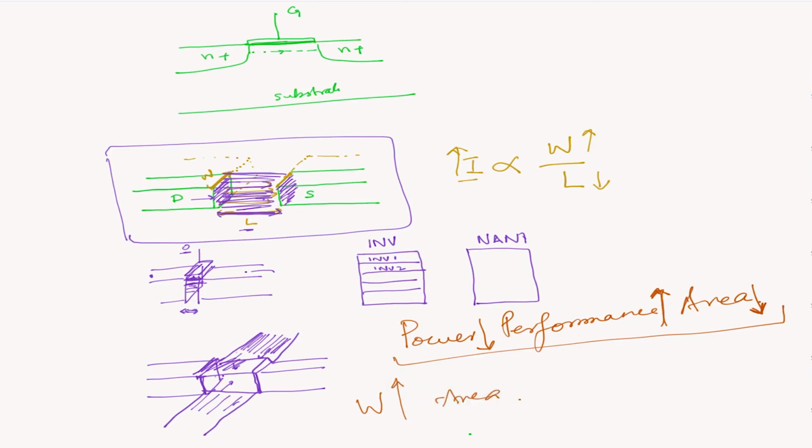So if you want to optimize a circuit for better area, you want to keep the smallest possible area, then you don't want to use bigger transistors with bigger length, bigger width. And as the width goes up, your frequency will get faster. So I mean, higher width would be good from a performance point of view. Okay, but higher width is not good for power.